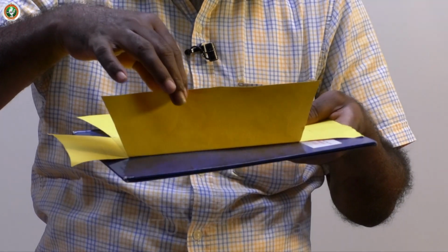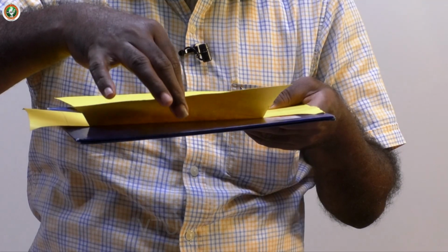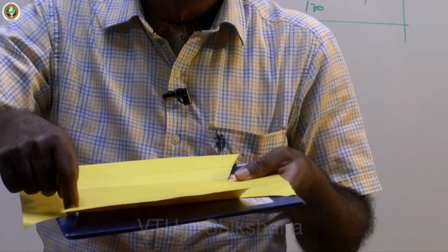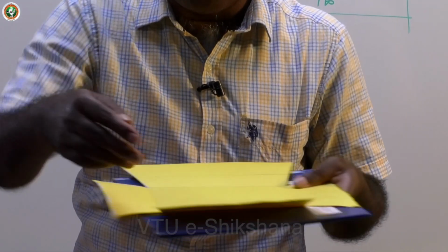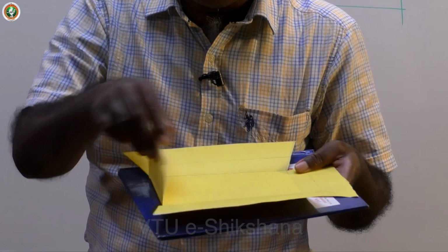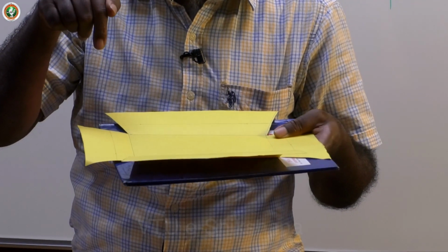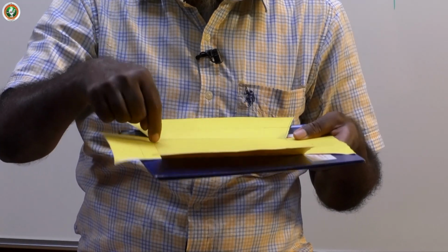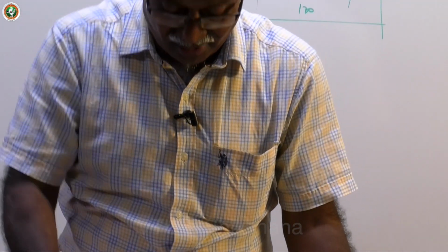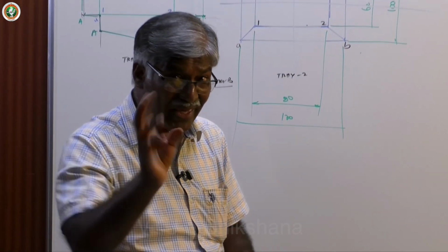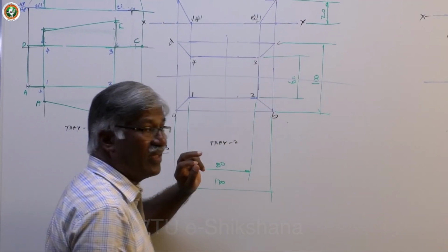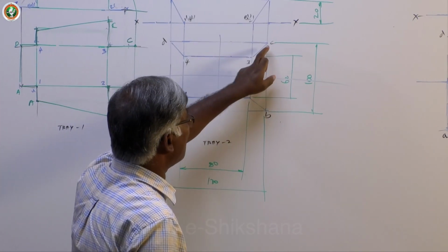A in this with respect to this lateral face is perpendicular to the base edge. Since it is horizontal, you have to draw vertical. What about this? Since it is vertical, you have to draw horizontal on the top view. Okay, so it must be perpendicular to the base edge, just passing through the outer corners. So from there, that is the moving end. For example, if you take a straight line, this is the moving end, this is the fixed end. So the moving end locus is this, starting from the moving end.